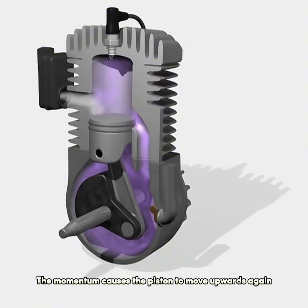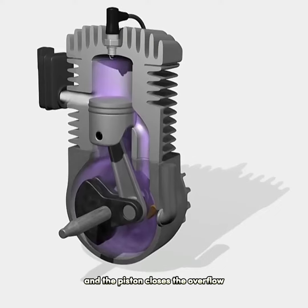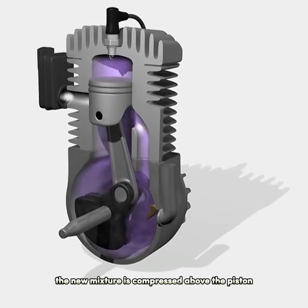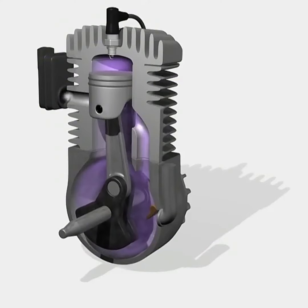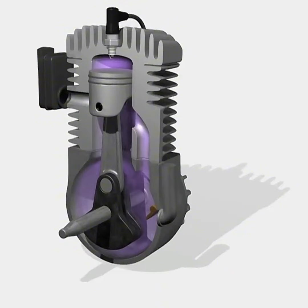The momentum causes the piston to move upwards again, and the piston closes the overflow and the outlet port. The new mixture is compressed above the piston. Something is also happening in the crankcase during this cycle.